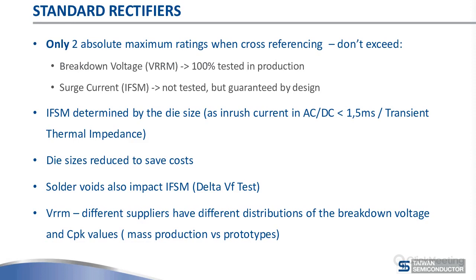The surge current, like if you have a 50 amp or 60 amp surge current, you cannot test in mass production. So it's guaranteed by design. Here you depend on the manufacturer to have good process control, for you to be sure that this is 100% functioning in your design.